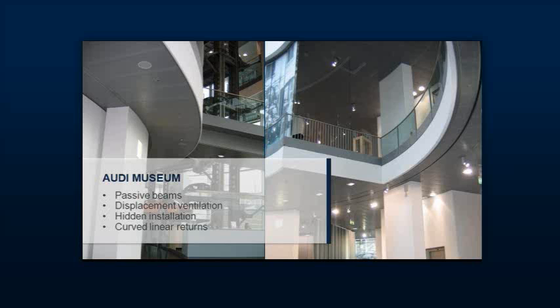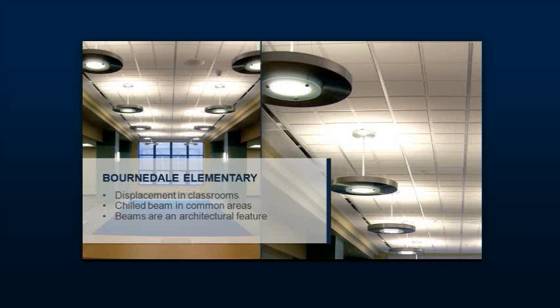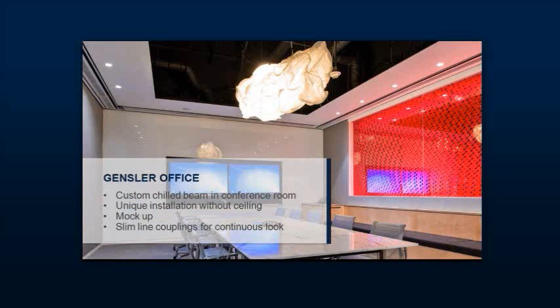What we have this do is we put it over, say, a heat source, or let's say it's over a window on the exterior wall, and any hot air rising off that window in the summer months would come in contact with the fins of this cooled coil. The air becomes slightly denser, and through gravity would then tend to fall toward the floor, and this induces room air through the coil. And you get a very effective heat transfer for minimal energy expenditure in terms of moving heat transfer in and out of the building. This is often used as supplements to displacement systems and active beams.